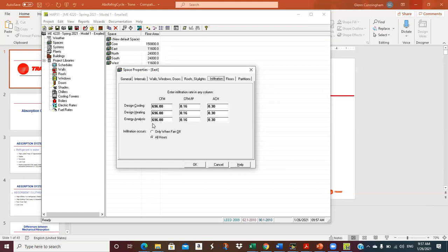So for this one, I made it really pretty good, even though it's almost 700 CFM, but you take a 270-foot exterior wall with all those windows in there and the wind blows up against it, you're going to get some air. Most wall constructions leak a little bit. You don't necessarily think about it, but with a 20-mile-an-hour wind blowing on that face of a brick and block building, you're going to get some air leaking through.